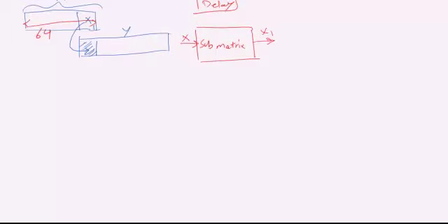After you have X1, the next part is how to merge X1 and Y together to get the whole block. The question is how X1 is going to sit on the zero padded part of Y. For that, you need another block in Simulink which is called Matrix Concatenate.